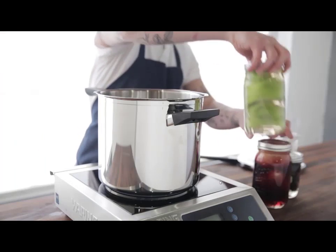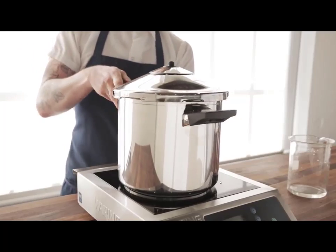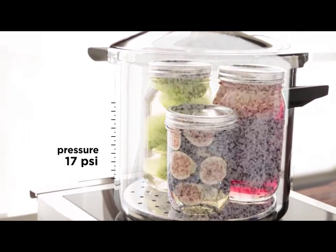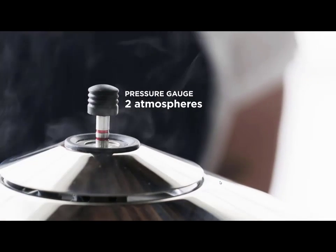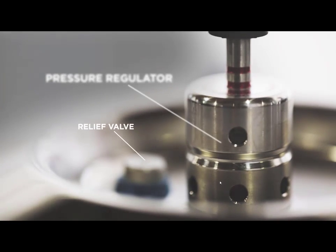Liquid is placed inside the pot with food, sealed in by a specially designed lid, and heated to the boiling point. Trapped and unable to keep expanding, vapors build up the pressure inside the pot. When this builds up to the cooker's target pressure, usually about twice normal atmospheric pressure, excess vapor is allowed to escape. Because of the increased pressure, liquid water in the cooker will stay liquid at a higher temperature than its normal boiling point of 100 degrees Celsius.